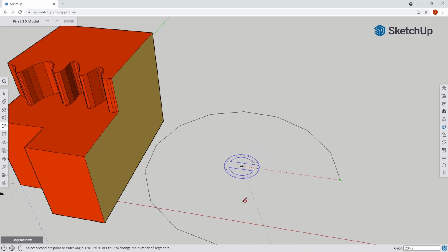And you might be noticing, hey, why does it go from being really smooth to all of a sudden becoming a little bit more resembling a polygon? That's a great question. Basically, when we create a circle, you'll see in a little bit that it creates a standard circle that has 24 sides, or sometimes 16. And so what you notice here is this one has 12. And so that's why it looks like a dodecagon or a 12-sided object.